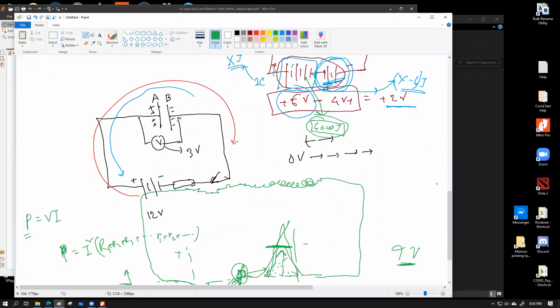Over time, after closing the switch, as current is slowly charging up this capacitor, the effective EMF of this circuit, or you can write the total EMF of this circuit, is going to be reduced, because at t equals 0, the capacitor did not produce any reverse EMF because it was altogether 0. So the total EMF was 12 minus 0 volt. That was at t equals 0 seconds.